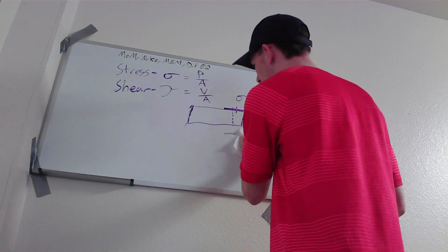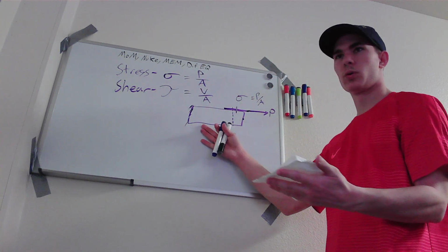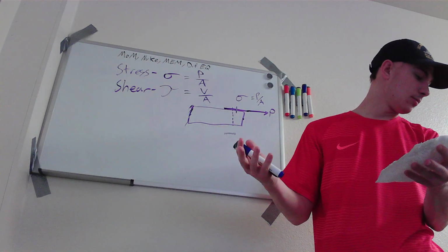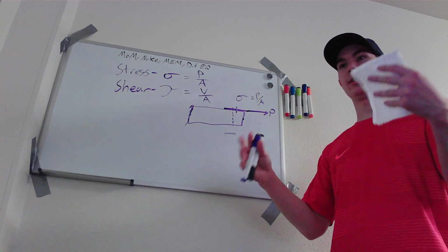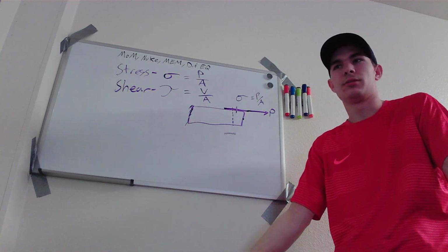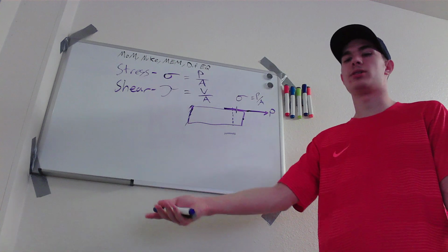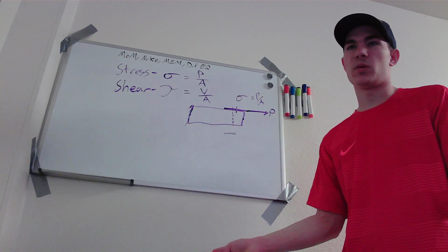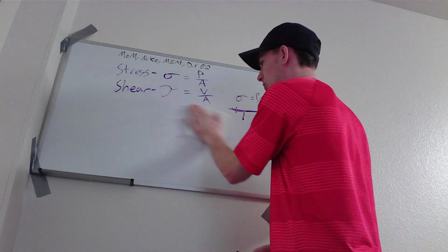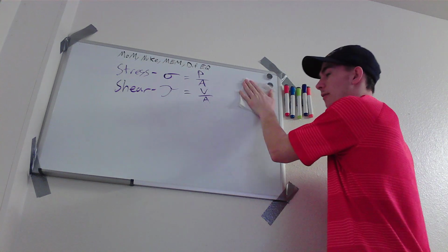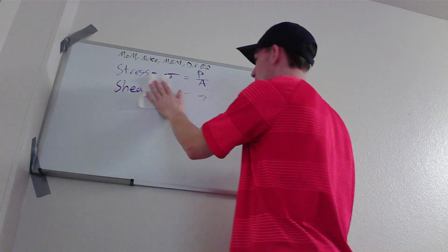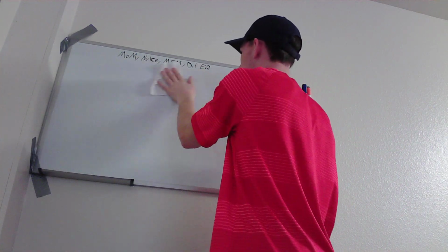There's some other things that we talked about, such as designing for shear stress and normal stress. It's like allowable stress design, ASD, is how they say, oh well, wood fails at 20 kips, 20,000 pounds per square inch. So we're only going to allow 10,000 pounds per square inch to be put on here. That's allowable stress design. So you design it as if 10,000 is the max that it can take, and that's how you would design it. That involves the design process.